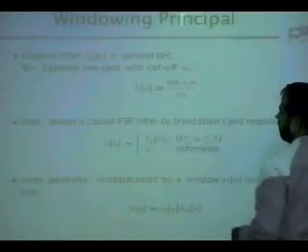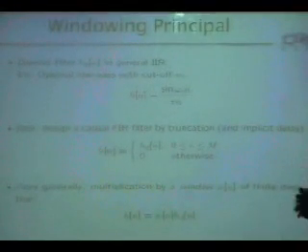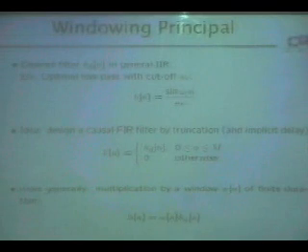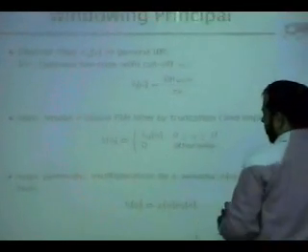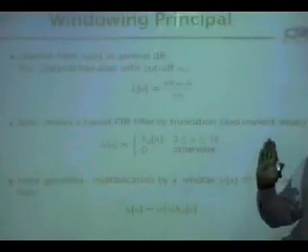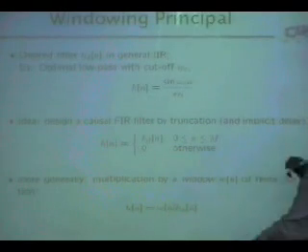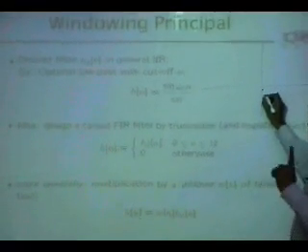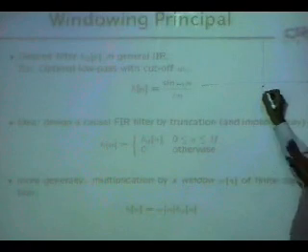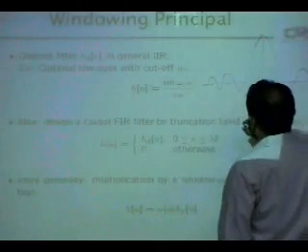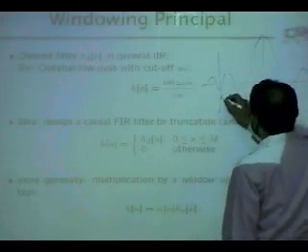So this is what you do. You delay it and then truncate it. You say, okay, first delay it and truncate so that you get a symmetric filter, one of those 4 types. Okay, so you get this, and this is really equivalent to this. The truncation is equivalent to delaying it and then windowing it. Okay, you first delay it, so the delay is by either an integer factor or an integer plus 0.5 factor. So you have this. Okay, and then you say truncate 0 to M.